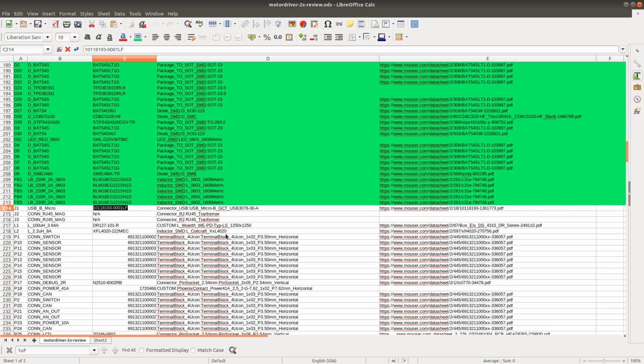because it happens quite often that because I'm copy pasting components when I create new components, I can sometimes forget some field, and maybe the component gets a wrong footprint, which would be very bad if that adds problems when the board is manufactured, and then new components have to be ordered with a different footprint. And that would be the best case. The worst case is that you get chips that have completely wrong footprint, and then you have to redo the board. So we want to avoid that.